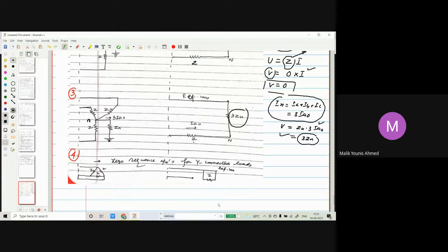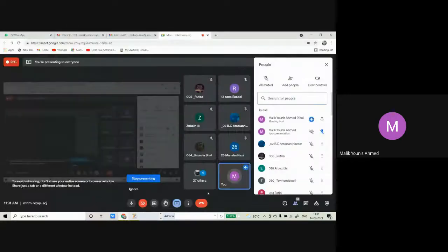So zero sequence currents may circulate inside the delta, since the delta is a closed series circuit for circulating single phase current. So inside the delta they can circulate, but otherwise here it will be an open circuit because of the infinite impedance. So this was the very important concept.